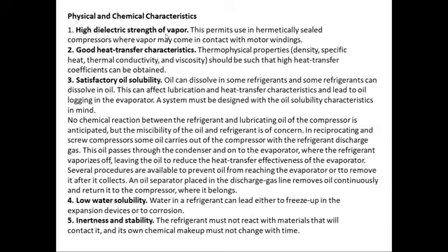Satisfactory oil solubility. This is one of the criteria which is very important. Initially, when CFC, chlorofluorocarbons, were used, the lubricating oil was mineral oil. But when we replaced it with halocarbons, HFCs, mineral oil could not be used, because mineral oil is not soluble in the halocarbons, so they stay separate.